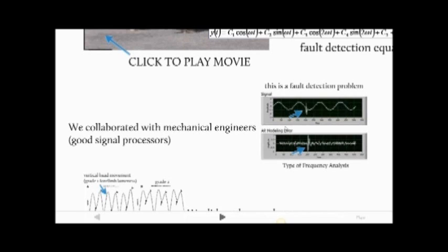If you bend or deform that structure in any way, then when it is stimulated, its response is now not normal, simple and sine wave-like. Now its response is perturbed and more complex with added components at different frequencies. And by inspection of this perturbation, you can be informed about the location and severity of the deformity in the structure.